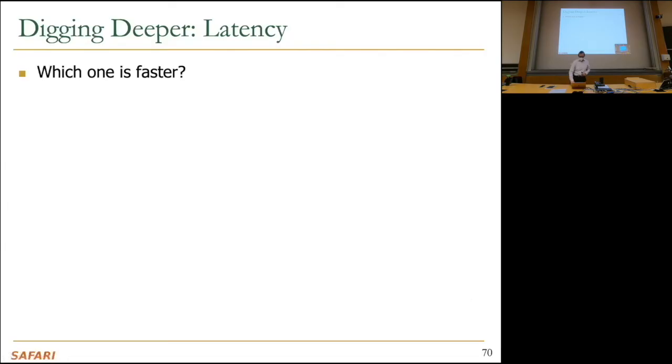Latency. Basically, latency means how long it takes for the output to become 1 or 0 given an input, right? So which one's faster is one good question, right? Are transistors in series faster, or are transistors in parallel faster? Any takers? Yes? Parallel, yes.